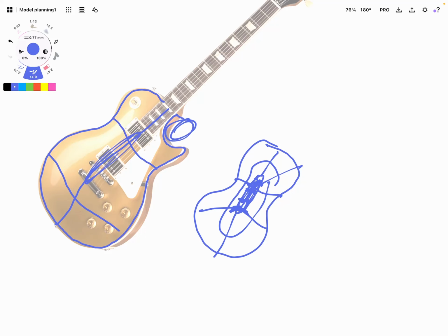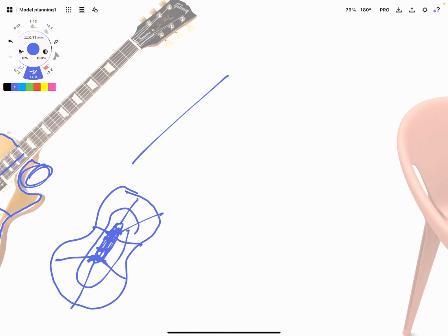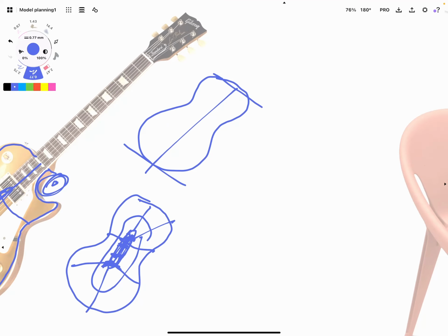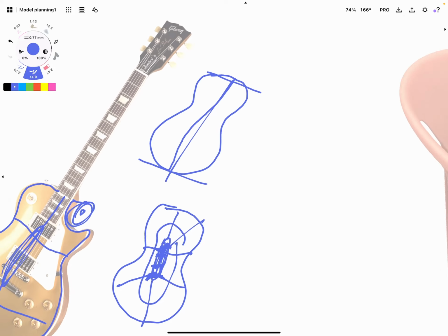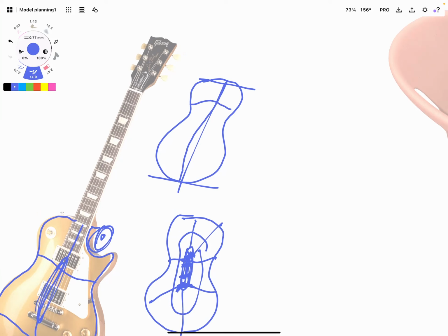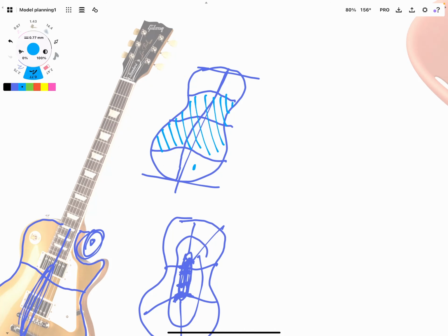I know you've got pickups and stuff through there, but a better way to do it would be to again ignore the cutout area over here, and then you draw the center line profile, and then pick a few areas like here and here, and another profile through here, and then you build that as your primary surface through here. And then to make the ends, we need to make that out of four-sided surfaces.